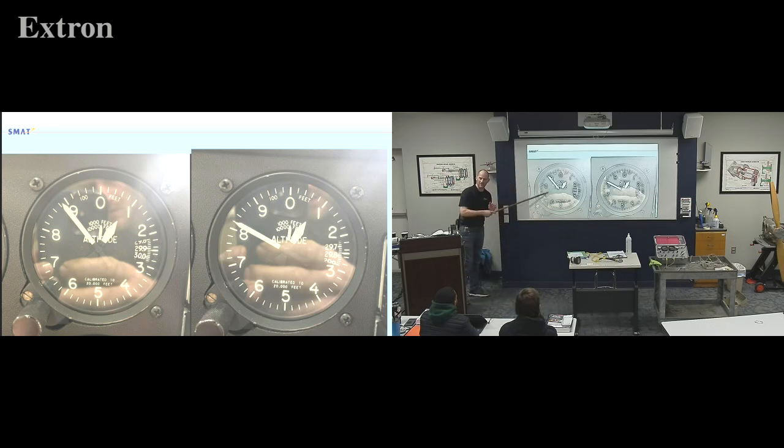What is this telling me? Next person. That one's telling me my, looks like Austin. I am not 800 foot off the ground because I'm sitting in the hangar, so it's not absolute. We'll take another name. Brian. Pressure altitude. We're set to 299 or 2, so it gives us our pressure altitude. All right, that is correct. So, setting it to 299 or 2, we'll read the pressure altitude.